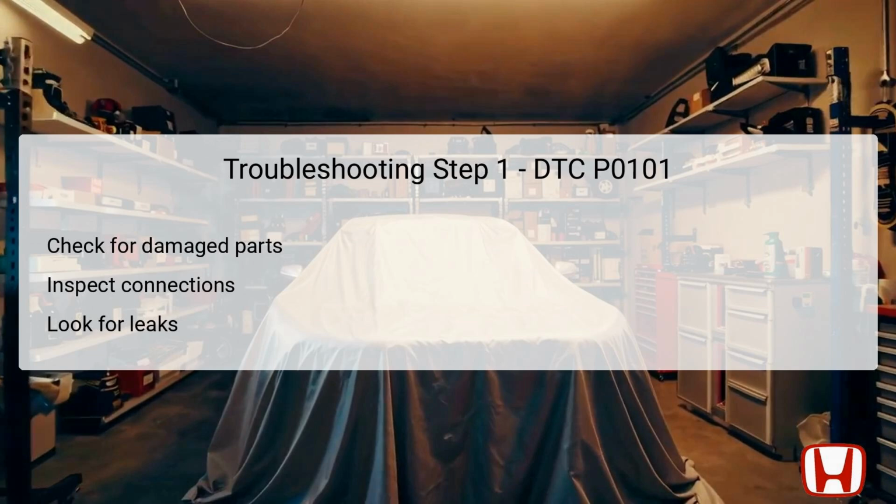The first troubleshooting step for addressing DTC P0101 involves conducting a comprehensive parts condition check. It's essential to inspect for poor connections or damage to vital components such as the PCV hose, intake air duct, air cleaner, and purge line.